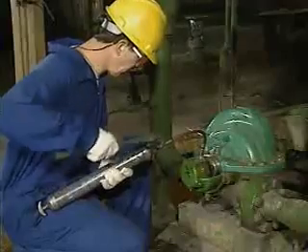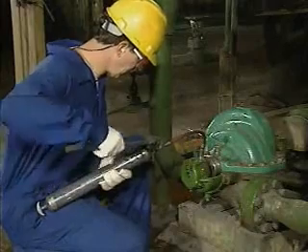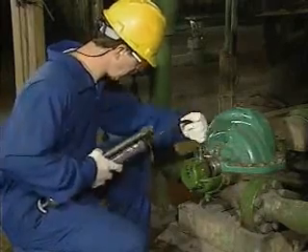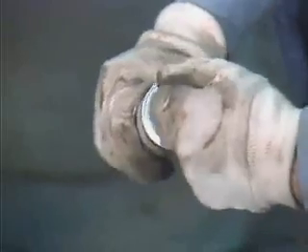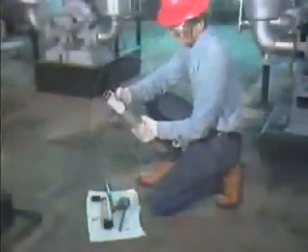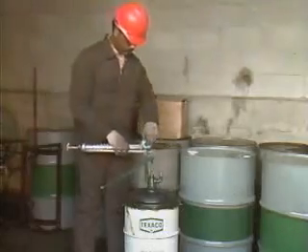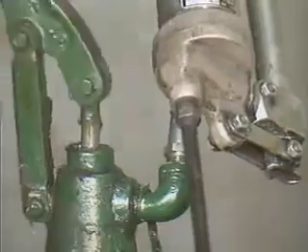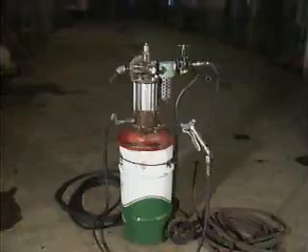In fact, grease guns can develop pressures in excess of 10,000 psi, which can damage seals. So you must operate grease guns with care. A very common way of filling some hand-operated grease guns is simply to slip a cartridge of grease into the barrel of the gun. Other types of grease guns can be filled quickly and easily with a filler pump that's clamped onto a bulk grease container, then attached to the gun.